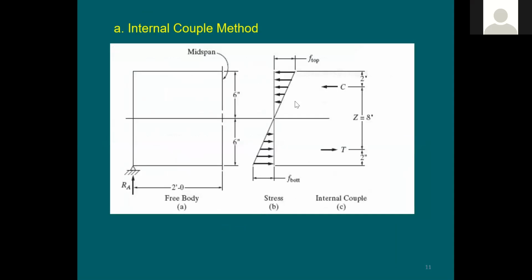Let's look here for the stresses. How can we do the stresses? And what can we do with this force, tension and compression? If this is 6-inch and you'd like to do some integration for this, where this point load is going to be for this compression. As I said, it's going to be at 1/3 of this triangle base. So if this is 6-inch, this is going to be at 2 inches, right?